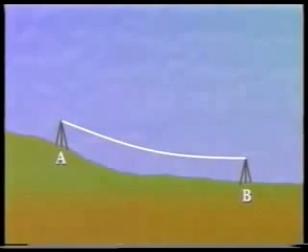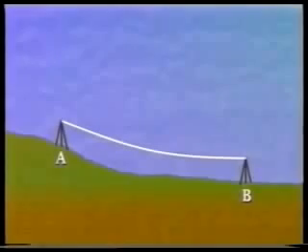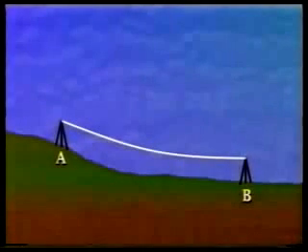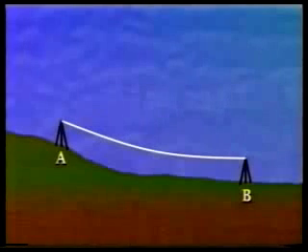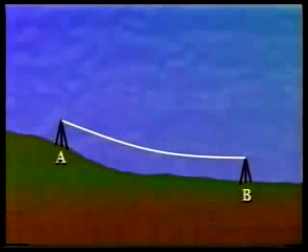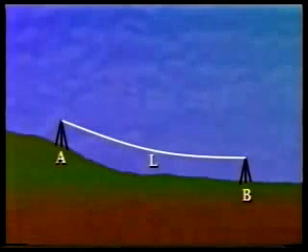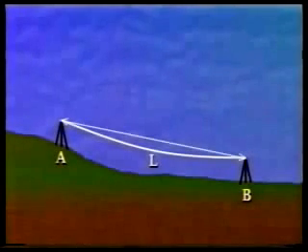The sag correction is also only applicable to steel taping and is only used on rare occasions when the tape sags under its own weight, forming the shape of a catenary curve. So it is also known as the catenary correction. It is usually necessary to apply a tension to the tape to keep it suspended. The measured length is L, and the sag correction is applied to this to give the straight line distance LS.